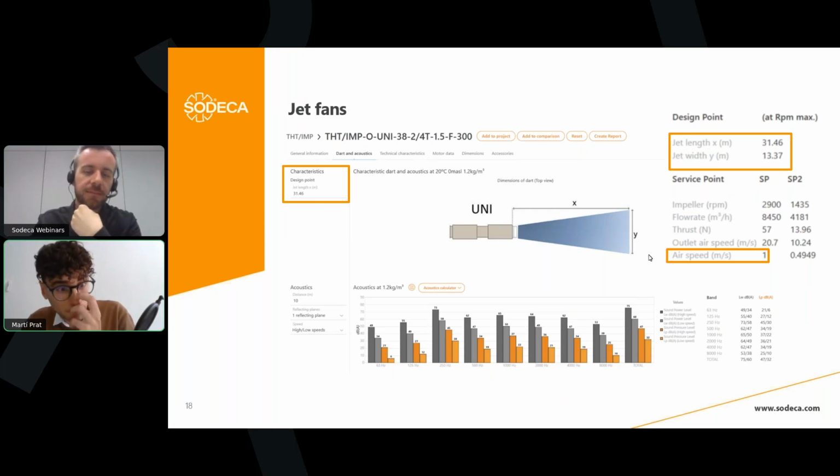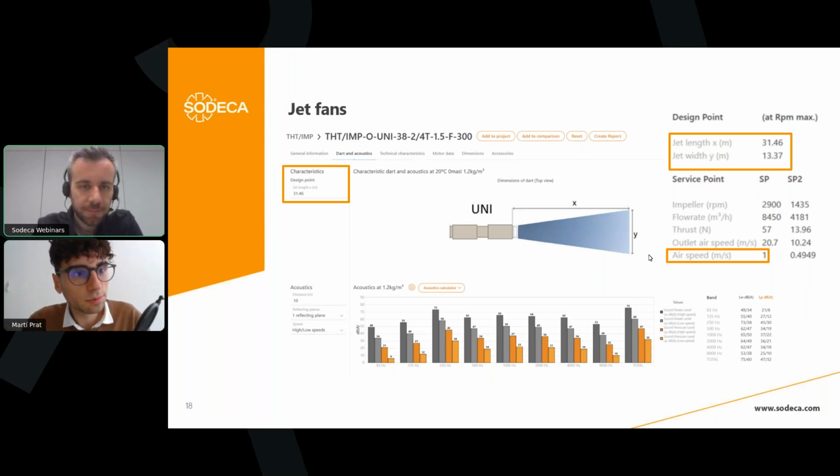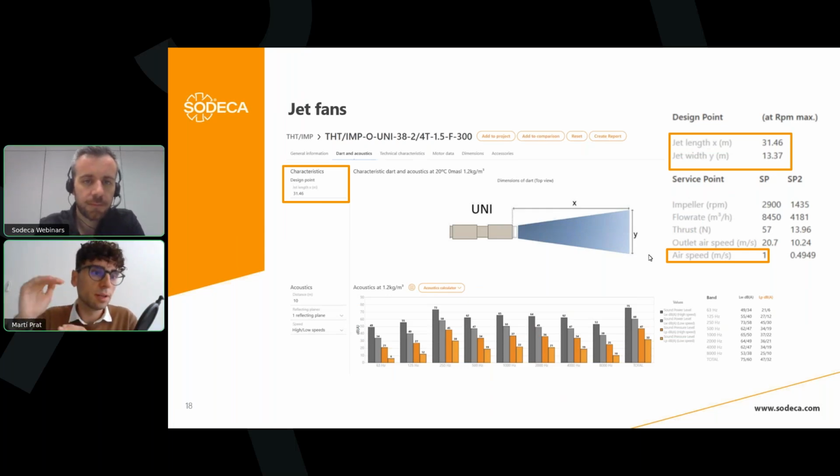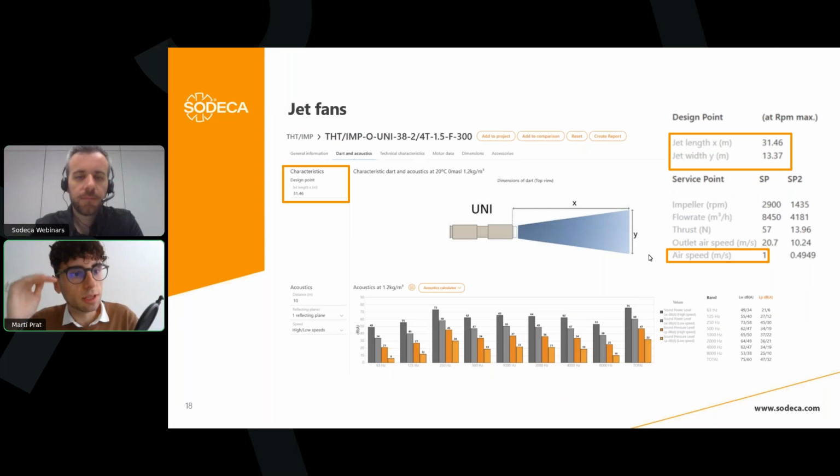It's true that when you have different fire zones or different zones in the car park, imagine that you have a multi-level car park with different basements, and the extraction and the supply is shared between these levels, you do the calculation of each level considering these 6 air changes per hour of air pollution control.